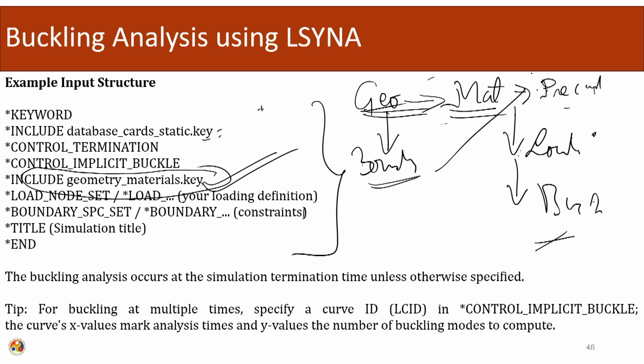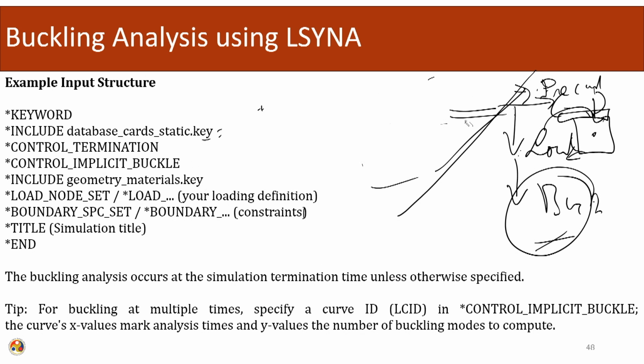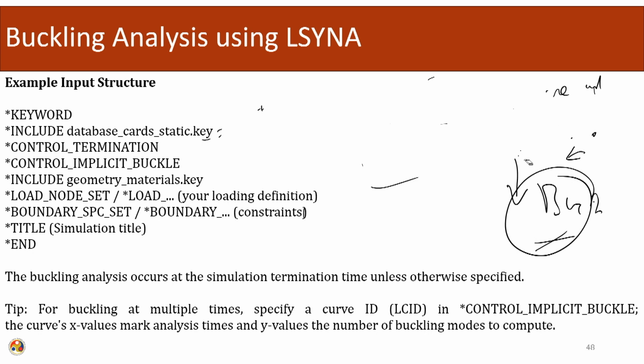After that, if there are any preconditions, we analyze these preconditions normally in a static sense, and we use these results to do the buckling analysis. Then we put in the buckling load, and after that we do the buckling analysis. So, these are some of the cards that are used in LS-DYNA to do the buckling analysis.